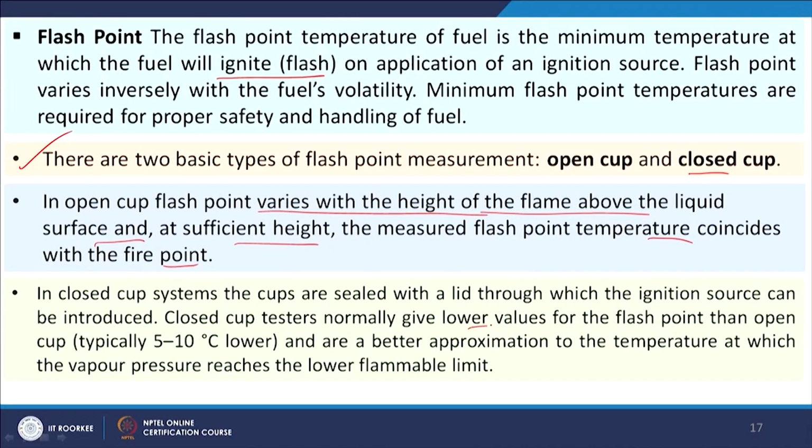But in case of a closed cup there is a lid, and we bring the ignition source for a moment and we get the flash. So, it has been shown that the value of flash point in a closed cup is normally lower than that obtained through an open cup, typically 5 to 10 degrees centigrade lower.